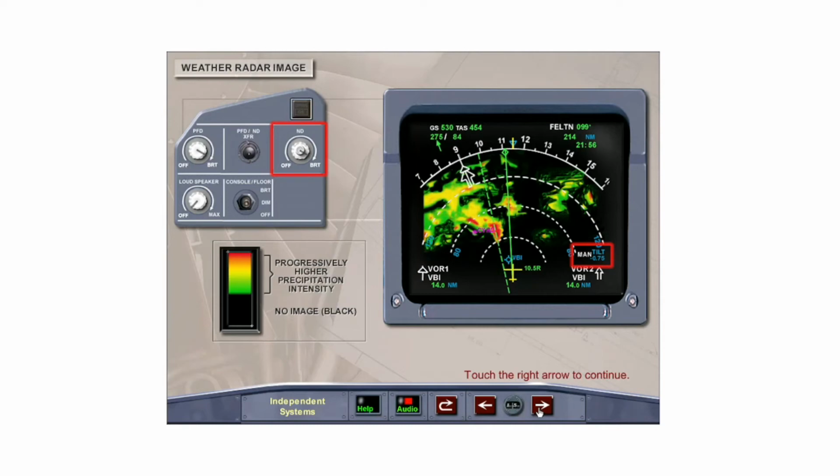of intensity. The antenna tilt between the horizon and the beam axis is displayed in degrees in the lower right corner of the navigation display. If the calibration mode is not in calibrate, then manual is displayed by the tilt display.